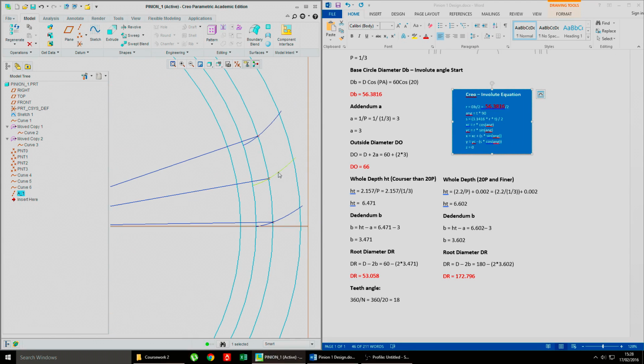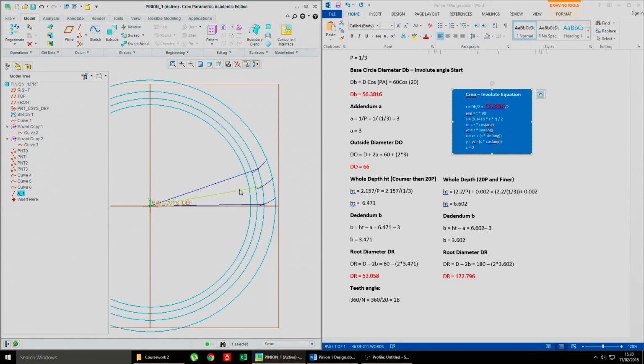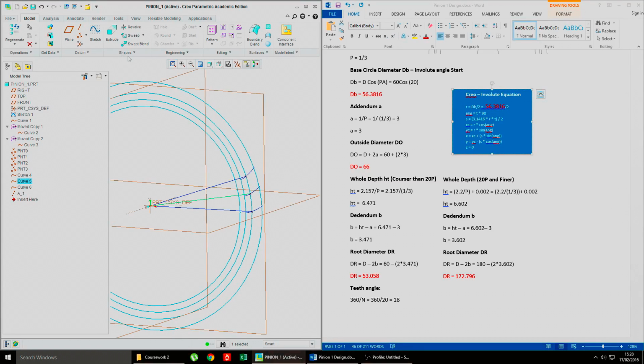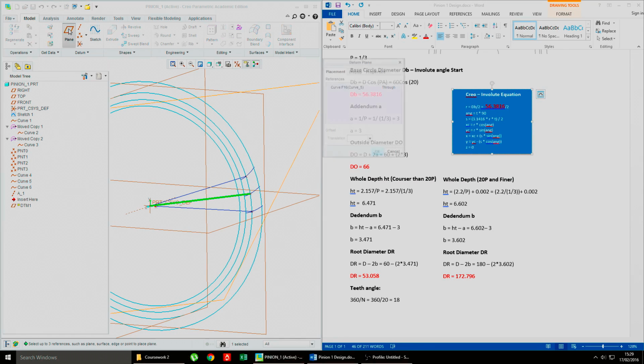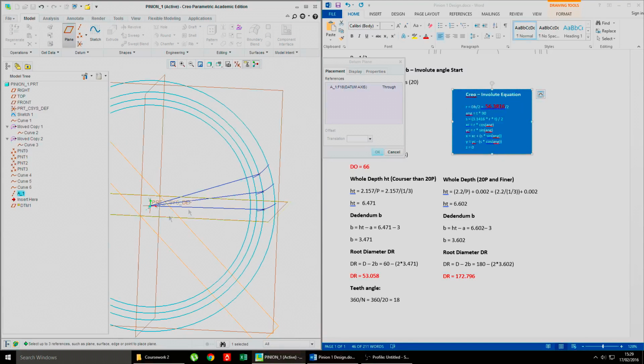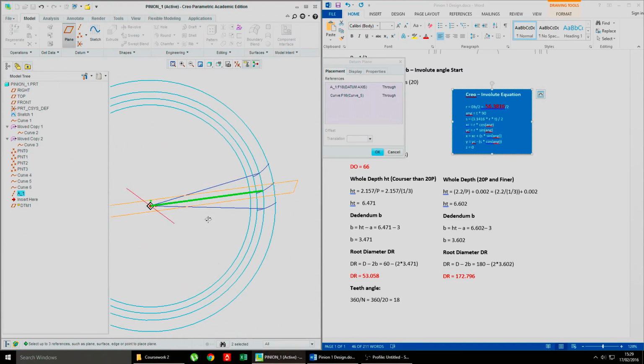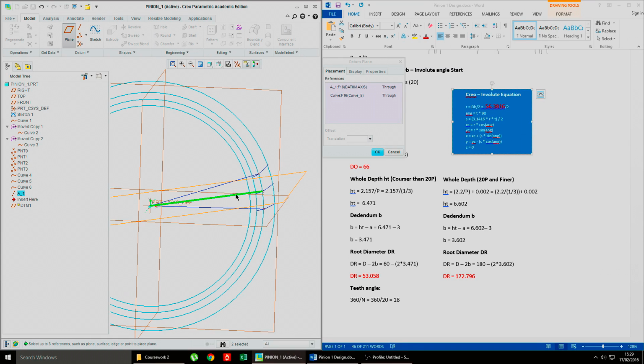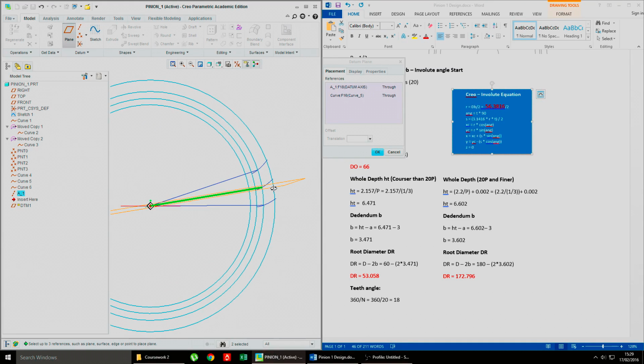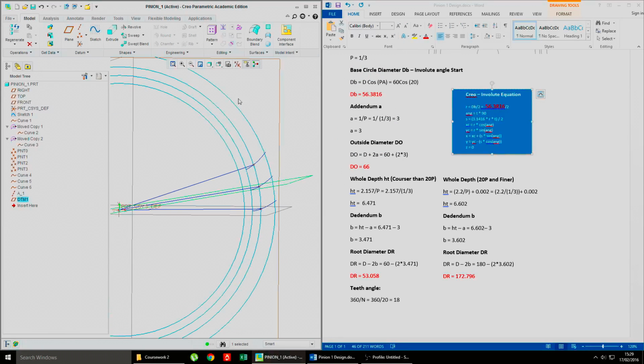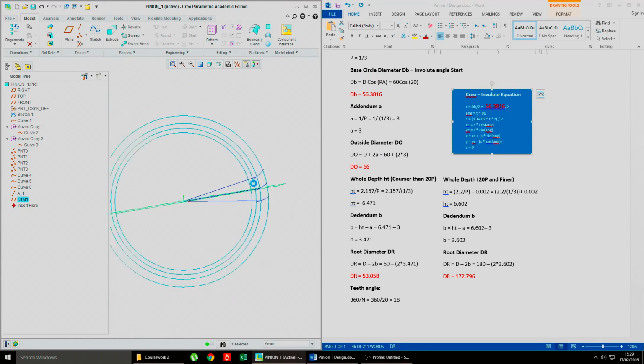What you want to do is mirror this curve in the middle, and the way to do that is use this line that you've created and that axis. So click on this line in the middle and click on plane, then click on the rotational axis. Didn't work, did it? There we are. So hold control when you click the line, hold control and then click Z. So click them both while you're holding control, and that will make a plane along that line that you created. Press OK. Put it in front view so you can see it's definitely on there.